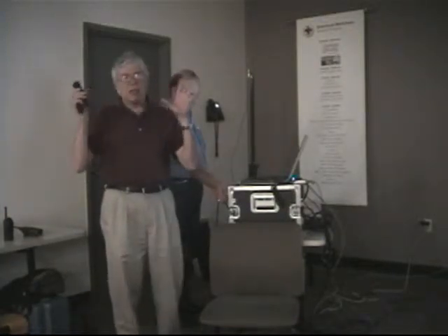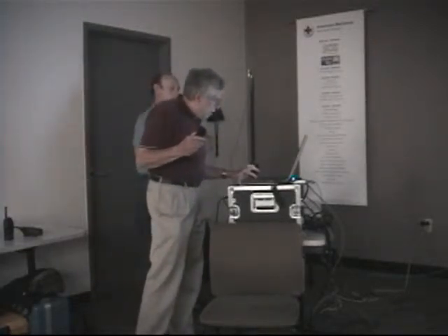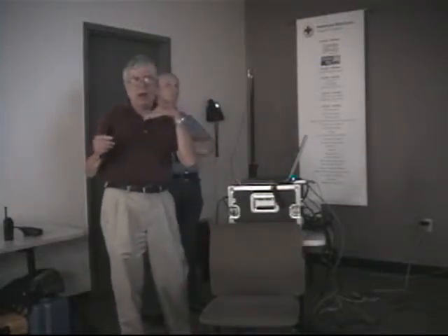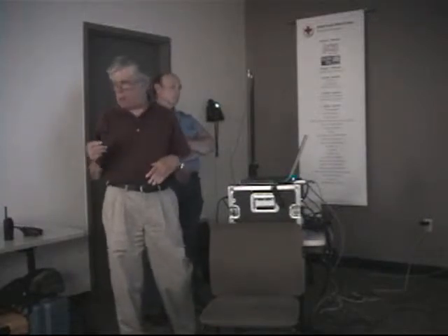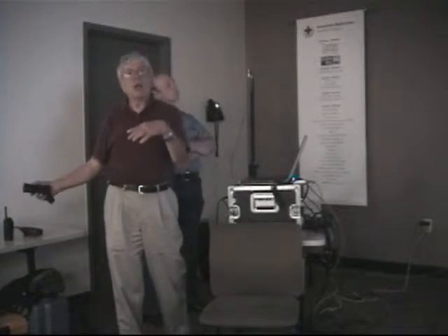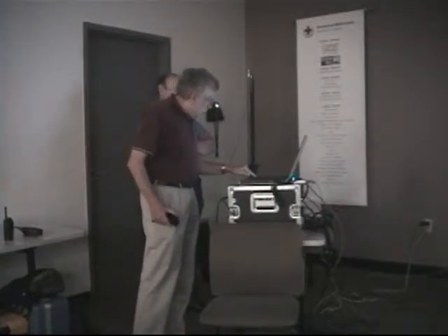Now that's the standard file from DVSI. And then what we did was we took this file and we filtered it to eliminate everything below 300 hertz, because a typical two-way radio doesn't use that spectrum for anything except PL tones. And so this is what a two-way radio would normally sound like.